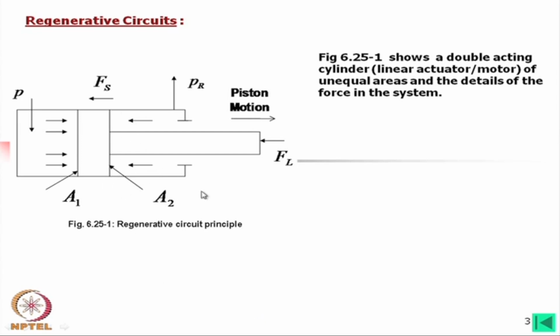Now, we can consider that there will be some friction force. This friction force will always act in the direction opposite to the direction of motion. So, this will be added to the load it is handling. This means that to calculate P we have to add this load with this load and then divide by this area.